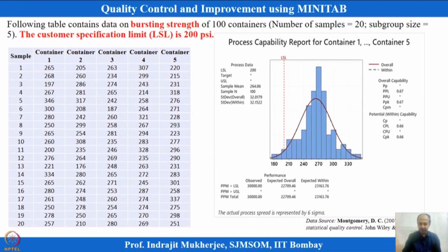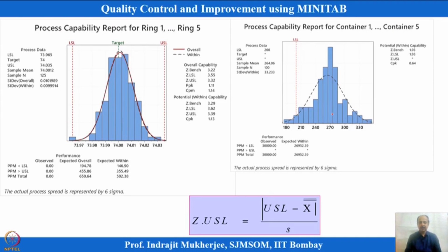And then this was a second case that we are reporting over here, and this is one sided. So, lower specification is this, anything below this will be rejection. So, it has to be higher than this one. So, this is one sided specification generally, that minimum this much is the strength that is required, 200 psi is mentioned over here, and for that, how to calculate process capability. Only thing is that you see that normality assumption seems to be satisfactory over here, but we can always check normality assumptions. So, this is the overall analysis of the two data sets that we are having.